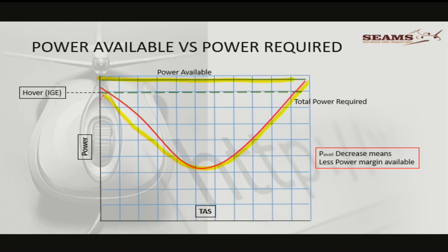And there is, remember now, the in-ground effect power required. This is what you require to stay in ground effect, and that is the power that you require to stay out of ground effect. But the top one is the power that you have available. So you have got all that way to play with, and there you've just got less to play with. All right.